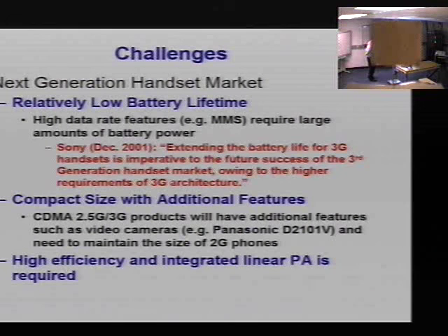Well, it's really a system-dependent question. What I think he's contemplating is that if for a very short burst I violated the linearity, and the soft decisions being put in the decoder are nevertheless correct, because the code is strong, it might still result in no errors. Right. It really depends on the system. Usually the systems which have hybrid ARQ are more tolerant towards this kind of stuff because at the worst case they just retransmit. And then there is of course the game of how short the frame should be.